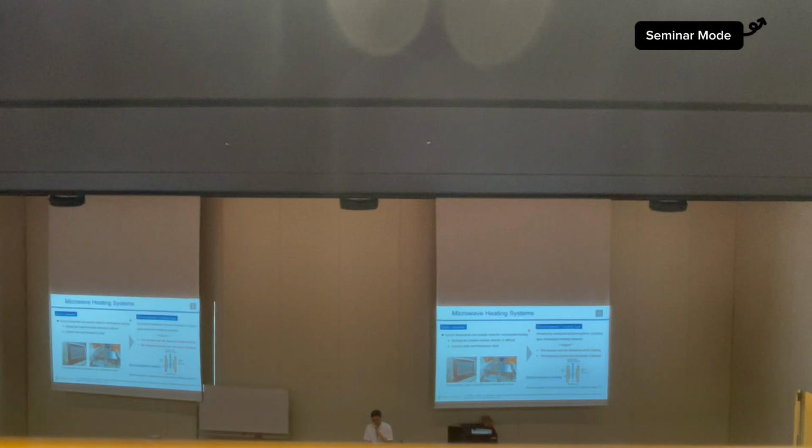On the other hand, a new type of microwave heating system, called the electromagnetic coupling type microwave heating system, was developed in my laboratory. This system contains two microstrip resonators on a substrate, and the heated sample is arranged between the resonators, and then the sample is heated by the non-radiative microwave from these two resonators.